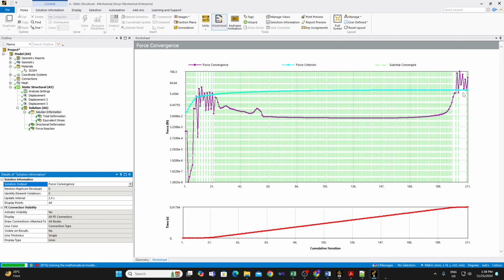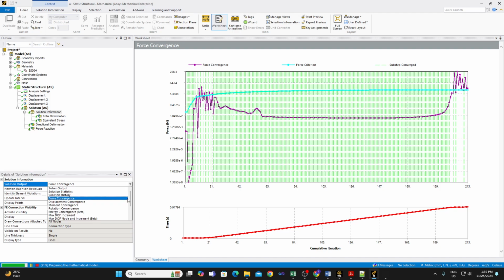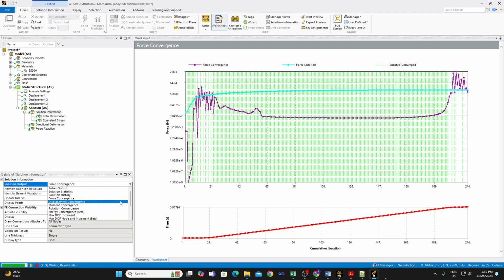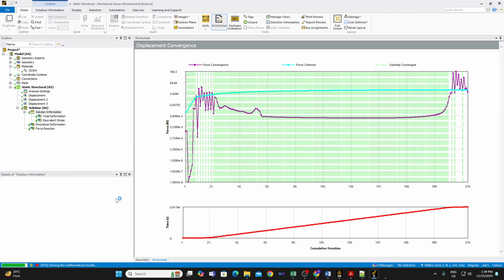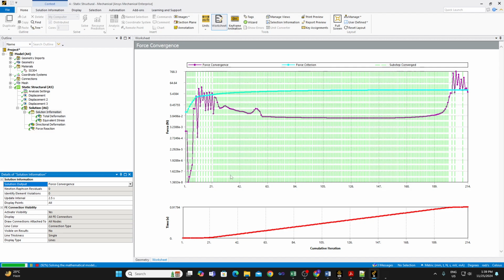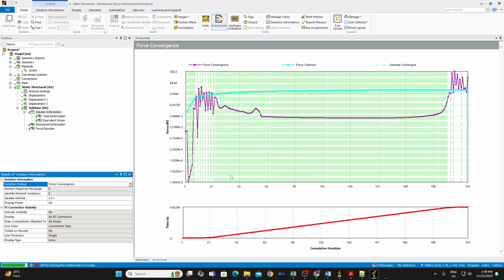Right now I'm anticipating that this will actually stop with the divergence. So let's just see what happens. It is already showing a nature where the bisection is due, because there are multiple iterations happening without the green lines, essentially convergence. The loading is displacement control, so I believe the issue is not with displacement convergence. The major issue is with the force convergence, because with displacement control, essentially the stiffness has become negative right now.